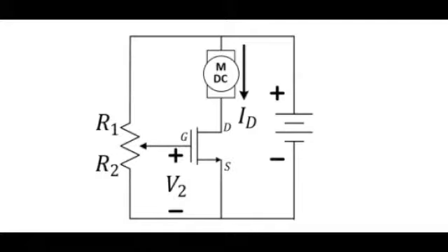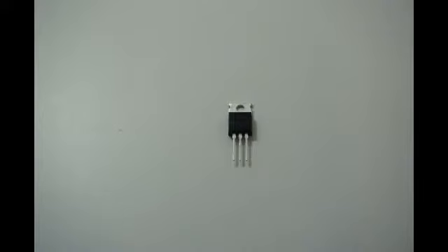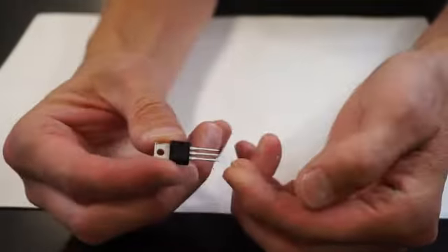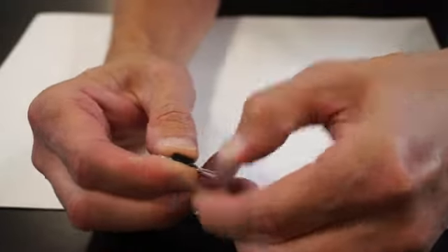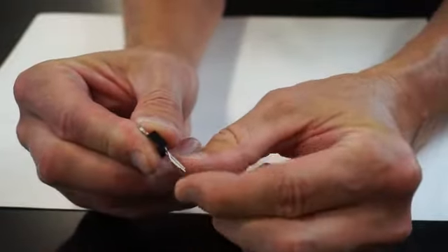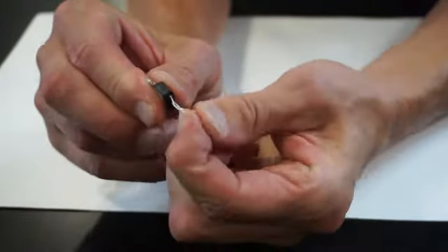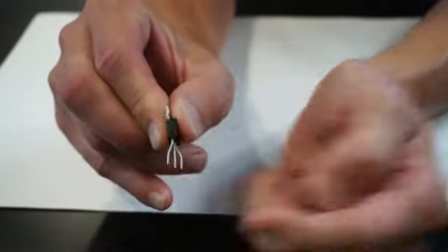We will now return to the car and build a motor drive circuit that uses a MOSFET transistor to separate the higher power function of driving the motor from the lower power voltage divider that sets the speed. Locate the MOSFET in your electronics kit and note the wide leads. These can damage your breadboard if forced into it. Instead, we will gently bend the gate lead back and the source lead forward so that the MOSFET can be safely inserted without overspreading the metallic clips within the breadboard.